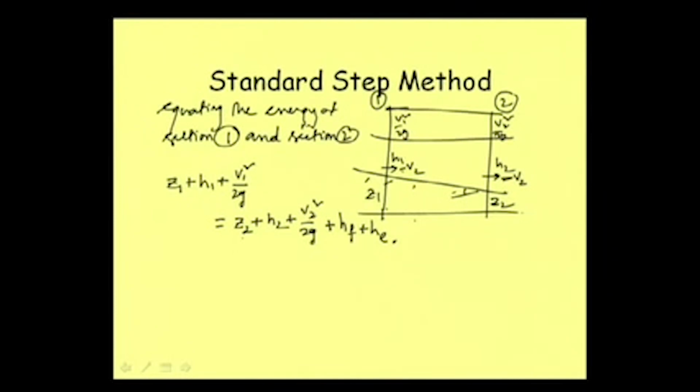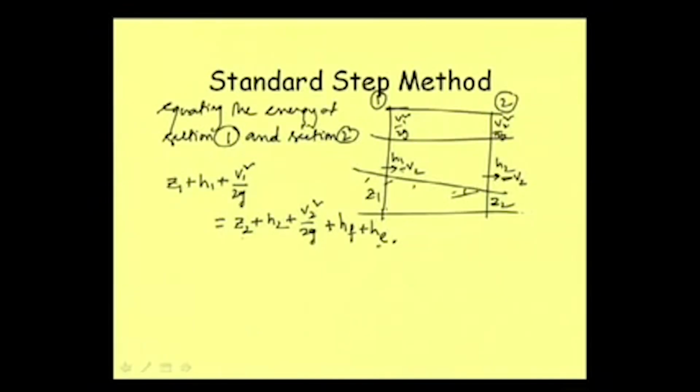If the channel is expanding or contracting, then this sort of eddy loss is important or significant. But if it is a prismatic channel, then this eddy loss is not that significant unless there is a lot of turbulence. And that's why, in the direct step method, that was also another reason why we cannot apply it to a non-prismatic channel. There we didn't consider this eddy loss.